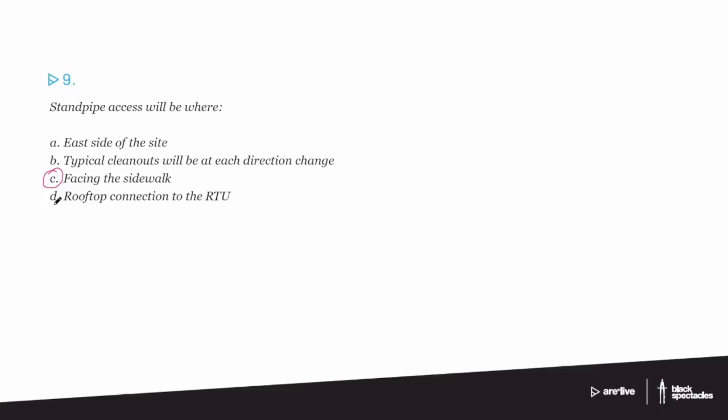It's then going to go inside the building and probably go right up to where one of the stairwells is, one of the egress stairs, and then it's going to go vertically right through the building. And then the firefighters can run up the building, and then they can tie a second hose from, let's say it's the 4th floor, they go up, they tie into the standpipe at the 4th floor, and then they can fight the fire. And that standpipe is now filled with water that has come from that fire hydrant that they just connected it to. So it's a way of extending the firefighters' hoses.